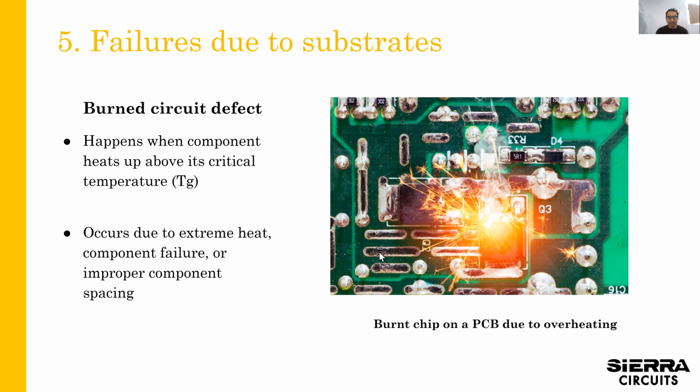The second thing I've seen customers do is instead of solder mask, they use flex material as a replacement to the solder mask, because flex material has better electrical properties. And so knowing the application, knowing what kind of heat's going to be generated, you can pick the right PCB material in your stack up.